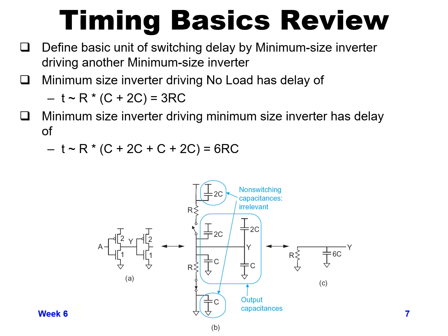If you look at the circuit figure below in part A, you can see a minimum size inverter is defined as a PMOS that is unit 2 connected to an NMOS that's unit 1 in order to make that inverter. The reason for that, again, is we want our rise delay to equal our fall delay. So in order to make the PMOS resistance, or RC in effect, equal to the NMOS resistance, it needs to be twice as wide.